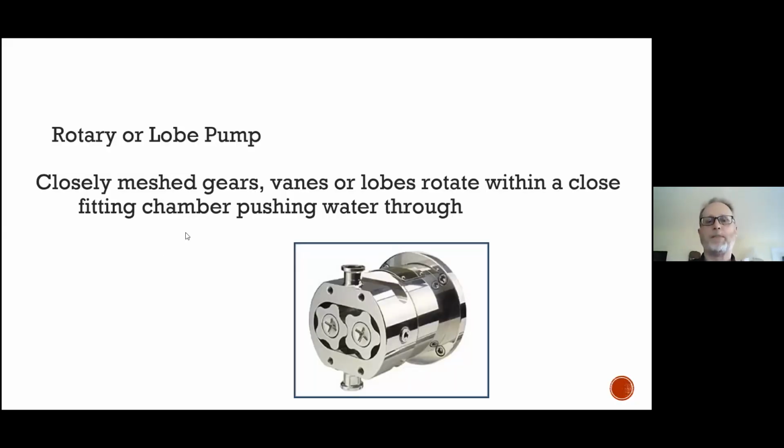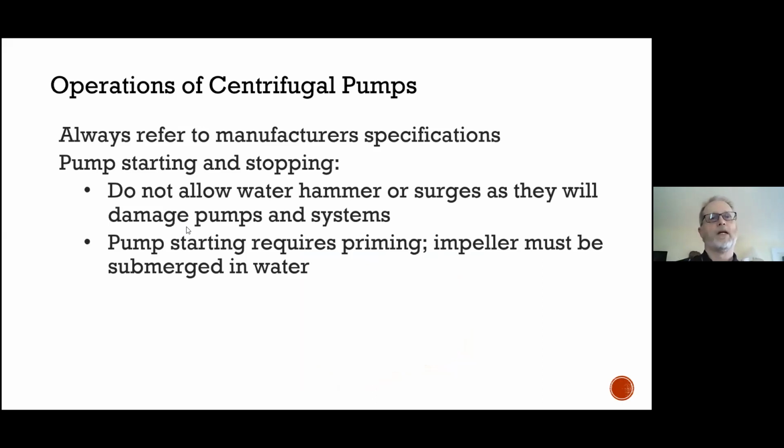So a couple of examples that we saw. The other key thing when we're talking about centrifugal pumps and operating them is we do not want water hammer or surges. And so that kind of gets back into closing the discharge side of the pump.